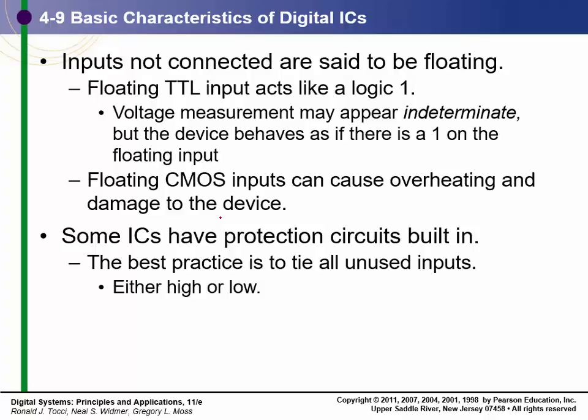Typically, if you're designing a circuit, the rule is that you tie all inputs, either high or low, whether you're using them or not. That's just TTL, it doesn't really matter, but CMOS, and I just made the comment that 90% of digital electronics are CMOS, therefore we should tie them either high or low. That's just a general rule. Like I said, even if you're not using that particular gate. The difference is that with a lot of the programmable logic, the inputs are automatically tied low internally.